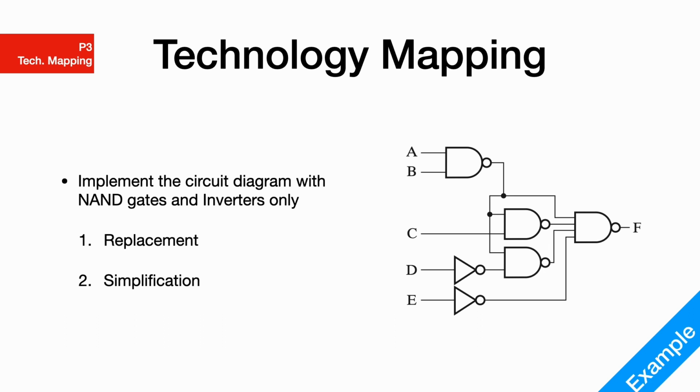This step is quite important because in technology mapping, as you discover more available physical components, sometimes you're aware of the presence of these physical components when you're optimizing your circuit, sometimes you might not be. This is why, even though we call it a 5-step systematic designing procedure, sometimes you do need to go back and forth between technology mapping and optimization, even though there's no error or bug being found. This is likely one of the questions that will, for example, appear in an exam or one of your assignments. The two steps likely to go back and forth with one another inside the 5-step systematic designing procedures are technology mapping and optimization. Depending on the technology you have at hand when you're trying to do technology mapping, the way you optimize your circuit could change a little bit.